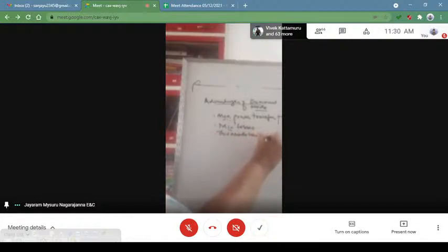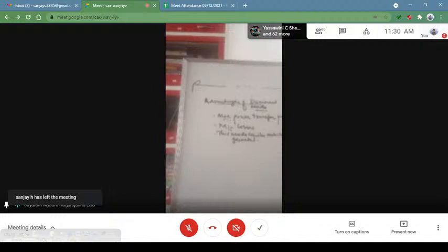Another thing is this mode can be easily generated. For each mode excitation, we have to use a combination of waveguide system or transmission lines and an antenna, generally used for exciting this modal pattern inside the waveguide system, by attaching this small antenna and the transmission line or waveguide section to the wall of the waveguide.